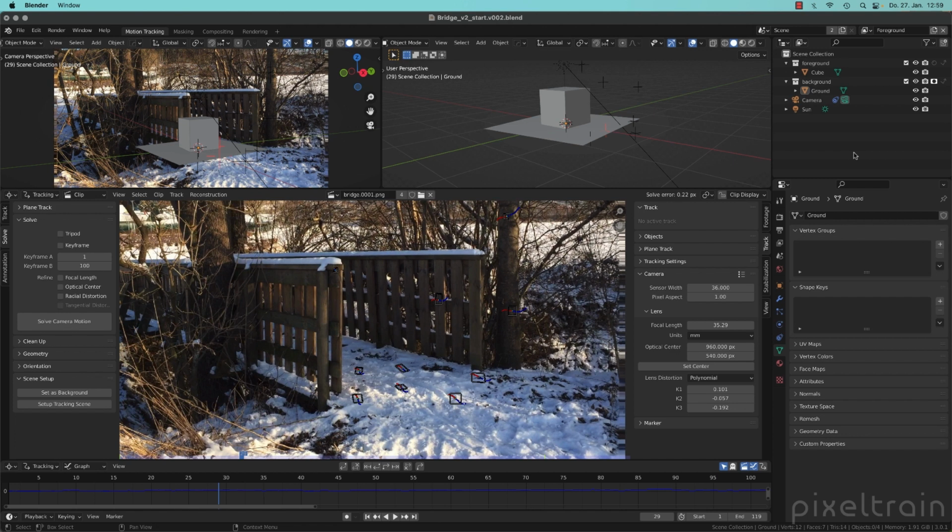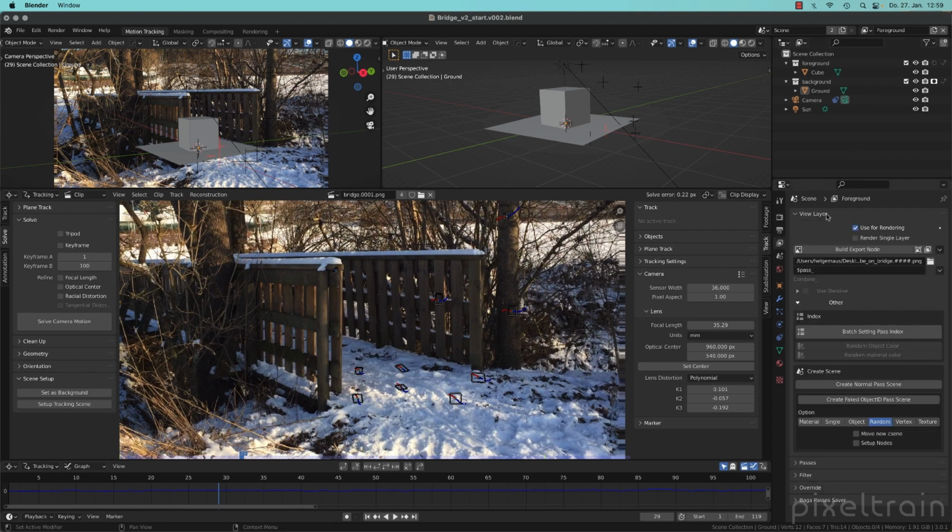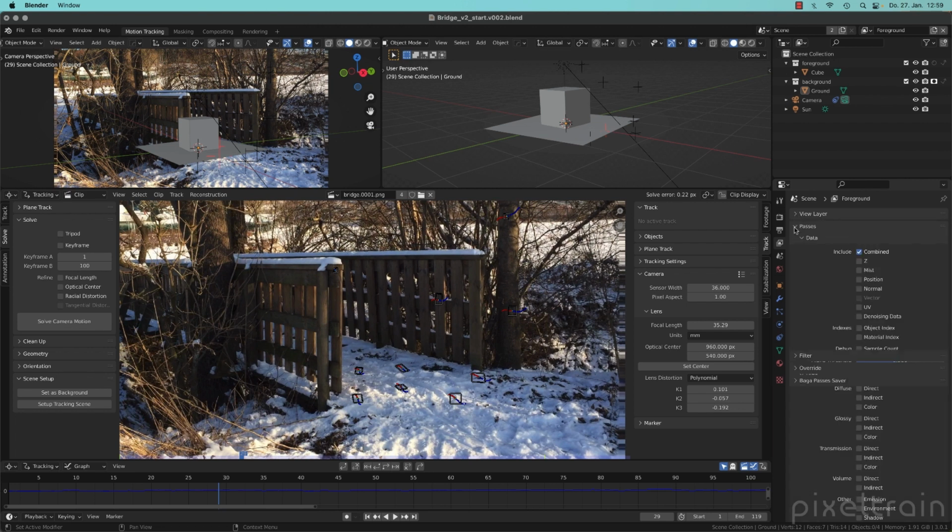Like I've said, render layers is a topic which is a little bit more complex. Refer to the other tutorials on my YouTube channel, but the idea here is, if you go here to the view layers now, these are the view layer options. Let's look into the passes here to see what's going on. Every collection here can store these options here, if they are active or not, and if they are fully visible and interact with everything, if you only want to see them as a holdout, or if you only want to have them contributing.